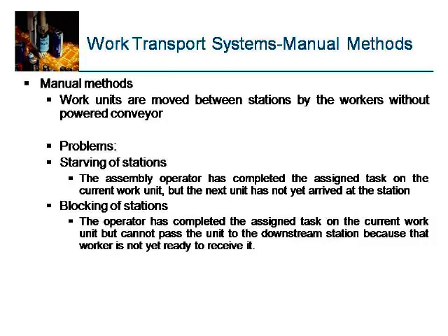And in this, a lot of problems are there, like starving and blocking phenomena happen. Starving: if the previous stage workers take more time, next stage workers don't have any work to do. That's how they keep on waiting for the work to be received from the previous station, and this phenomenon is called the starving phenomenon.